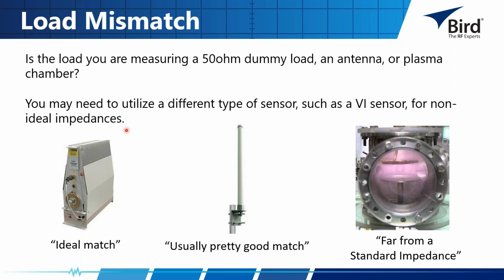Most of the time, in all the systems we're working in, especially the comm side and broadcast, we're thinking in terms of 50 ohms. We know there are small deviations around that, and that's what we're characterizing with all these mismatch pieces. But as we start to stray towards other types of loads and applications, we get impedances that stray much farther away.